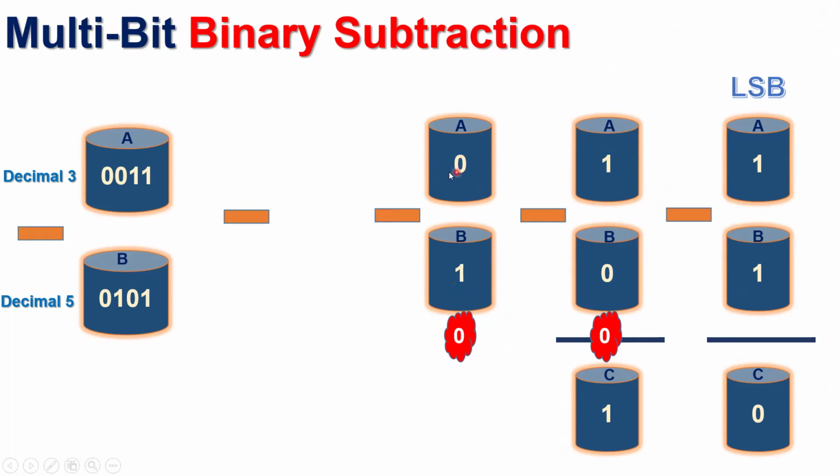This in binary, then this number is 1, 0. In decimal, it is number 2. And we will read as if we are subtracting 1 from 2. So 2 minus 1 will be 1. Or in binary, 1, 0 minus 1 will be 1. Of course, now the borrow out from this bit position is 1, which becomes borrow in here.